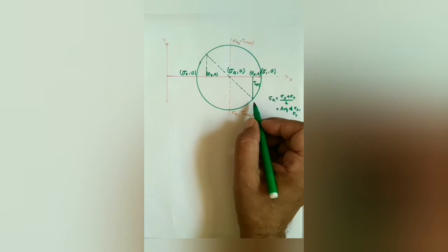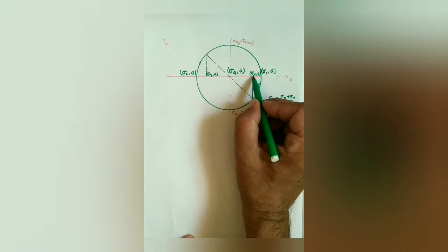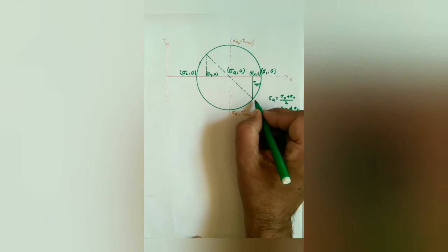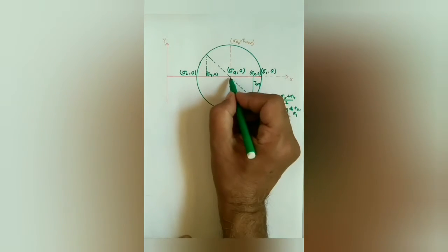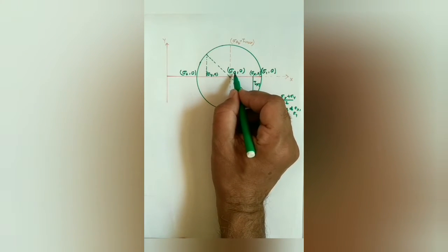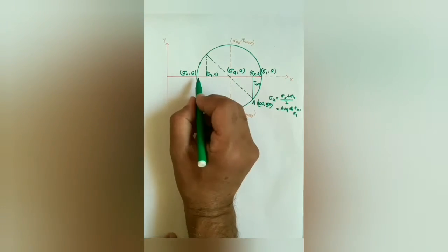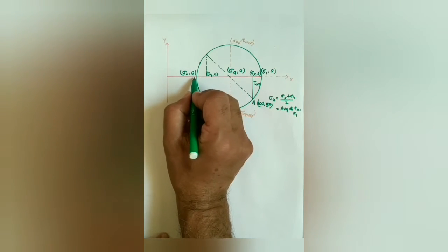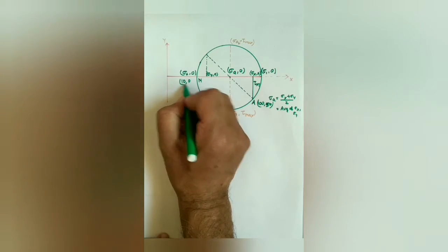Data is available on Mohr circle in the problem. Sigma x is given 100 and tau xy is given 50. So the coordinate of point A will be (100, 50). Center is sigma average, that is average of sigma x and y, and 0. Sigma min or sigma 2 is given 10. So the coordinate of the point, say N, is (10, 0).